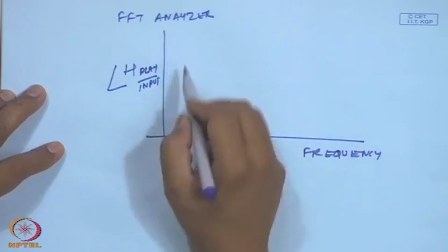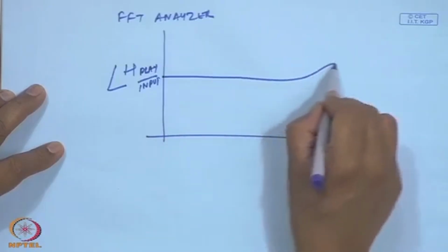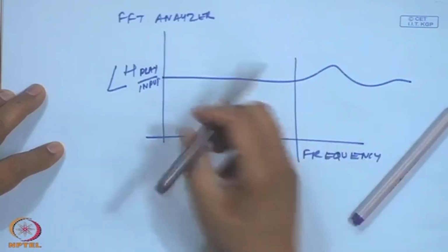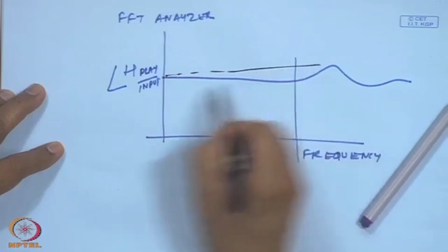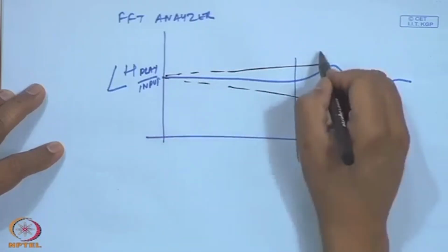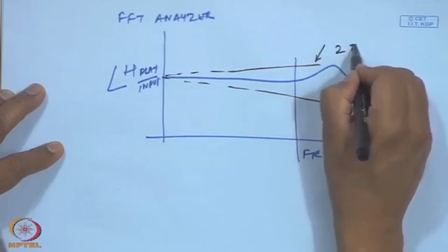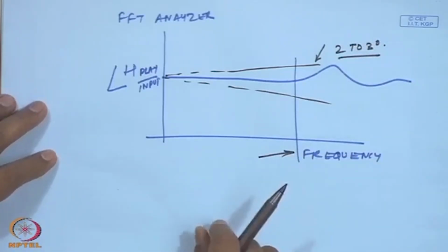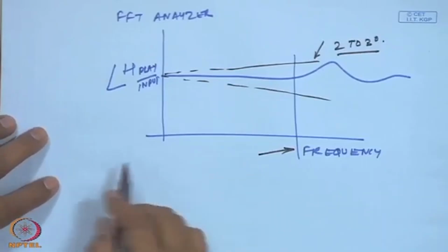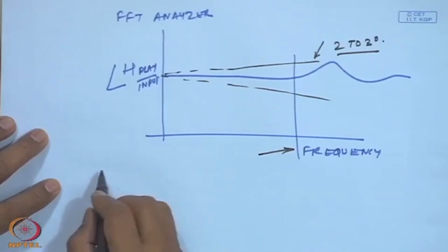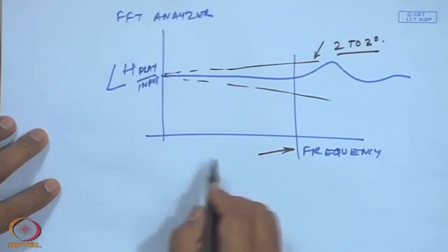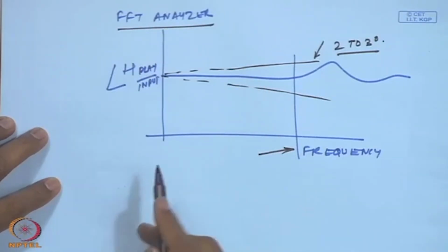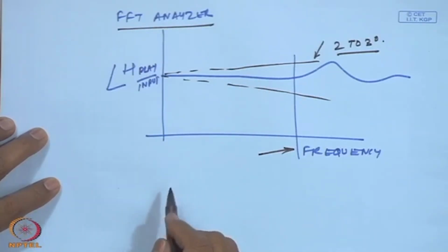This phase angle should also not vary, and typically these phase angles are of the order of 2 to 3 degrees. So then you can see the frequency limit of the signal. The upper frequency limit is decided by doing such a small test using a random noise in a DAT recorder, and you could use that same technique in a digital recorder as well.